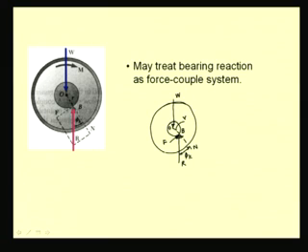Now, I can replace this resultant force R by a force that passes through point A, which is the lowest point of contact, just below O, the center of the axle, and replace this by a force R and the moment due to this force acting at this point B. So, this is the force R acting at A and a moment M, which is equal to R r sin phi k, which we just found is approximately equal to R times r mu k.